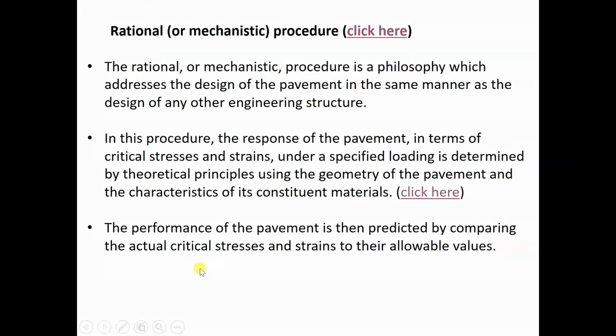The traffic loading maybe, for example, 7 times 10 to the power 6, so that means 7 million ESA, within, let's say, a duration of 10 to 15 years.